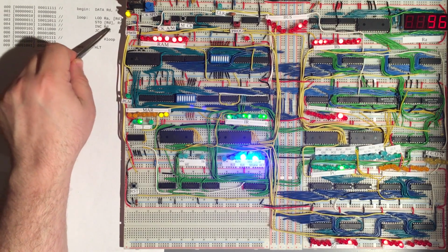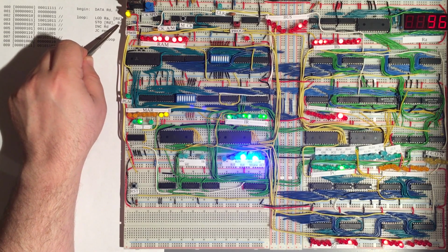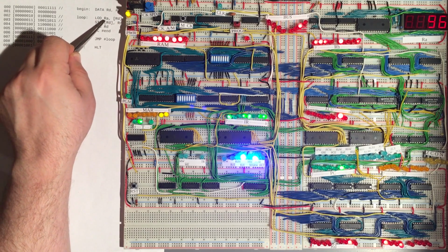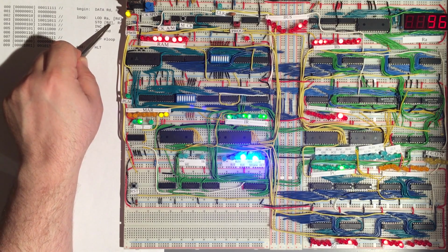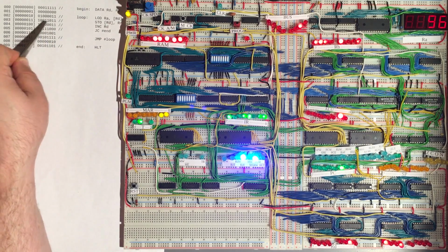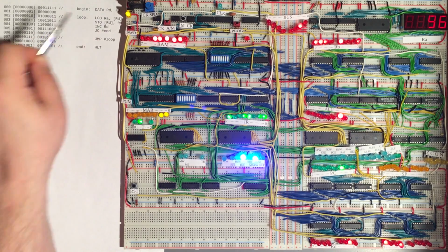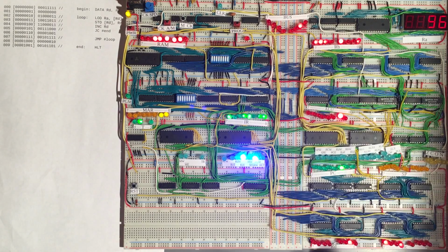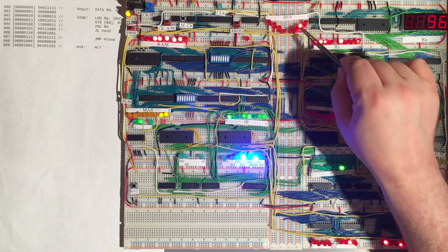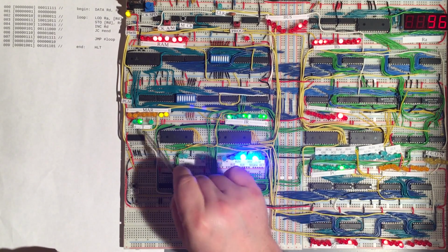And so the store instruction, what it will do is it will take a value from some register and it will then write whatever is in that register to a specific address in data memory. And the address where this value should be written is in another register. And so once again, the first thing we need to do is to point the memory at this address. And so we need to get that register out onto the bus. And so the D register is enabled onto the bus, so that value goes onto the bus. And we need to write that into the memory address register. And so that value will go into the memory address register on the next rising clock edge. And so that's the microcode for time t2 for the store instruction.